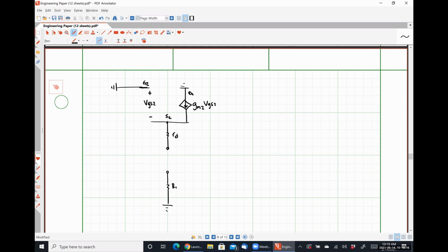Here's my resistance R22, right? And I'm looking in through that open circuit network to figure out what's going on. So one thing that I want to be clear here, we can tie those two drains together, those two grounds together, when I draw my equivalent circuit to figure out what's going on here.